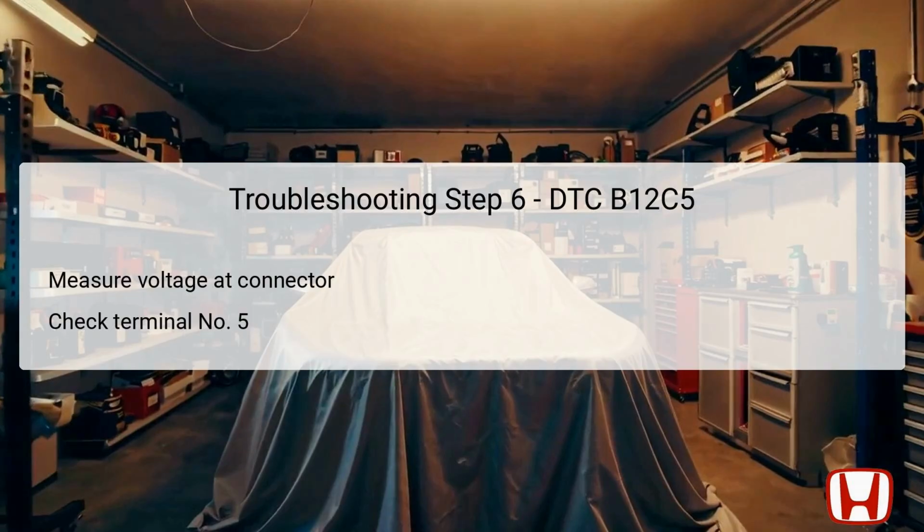However, if the voltage is absent, it typically points toward an open circuit or high resistance within the wiring. Repairing any found issues with these connections is essential to restoring the switch's operational integrity. This voltage testing ensures that the electrical supply is consistent, signaling that the system is potentially in order up to that juncture. The seventh step directs technicians to press and hold the engine start-stop button.